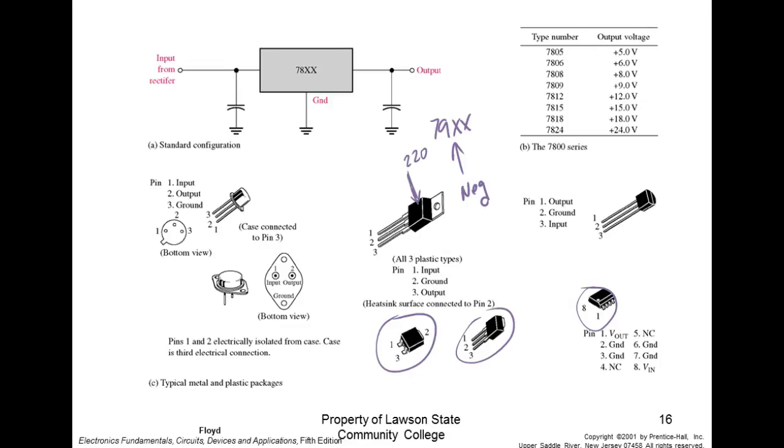And it's a very simple circuit. You need this one. I'll have to look this up too. I think I've got the 7800 series regulator sheets up on Blackboard, and they would tell you the size of this post filter right here. This is required depending on how far you're away from your main filter. These guys are really easy to do. 3 terminals. One side is for what?